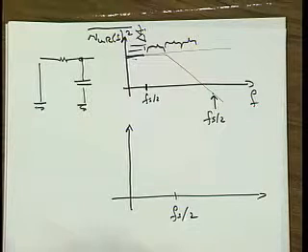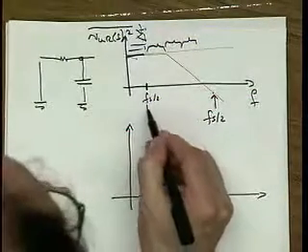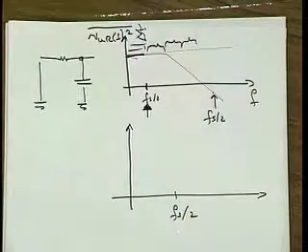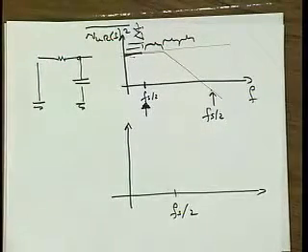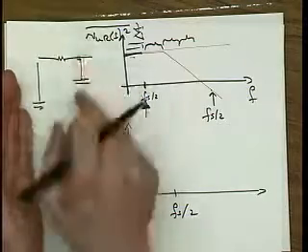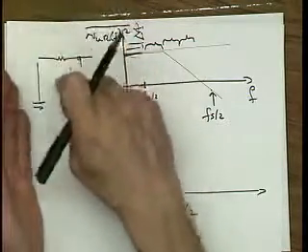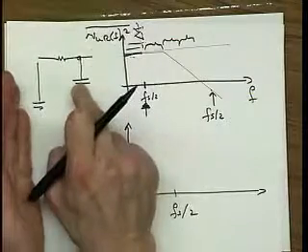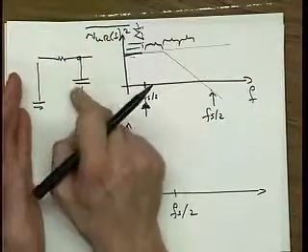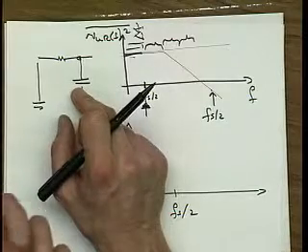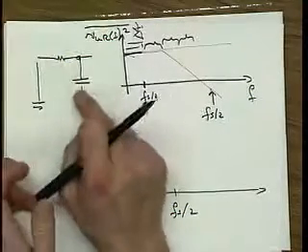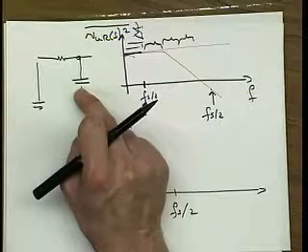Okay. So then we have to ask ourselves the question, well, what are we going to do? What do you think? Well, I can tell you. Most of the time, almost always, if we are here, then there is something terribly wrong. Why? Well, because most of the time there is an amplifier, of course, that produces a signal here, and we want to catch that signal onto a capacitor. Well, we want to catch it faithfully. In other words, we want the signal to really have time to settle to its correct value on this capacitor.